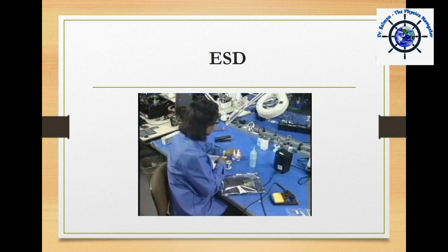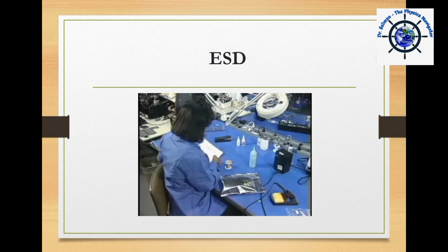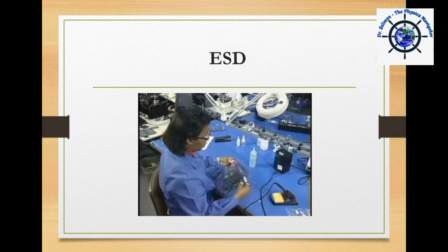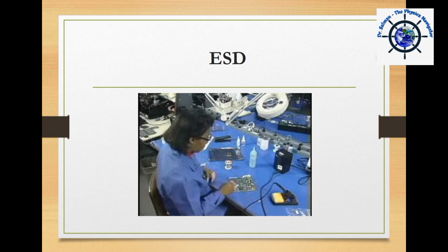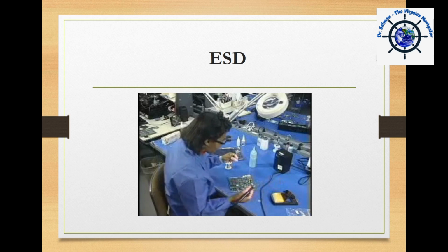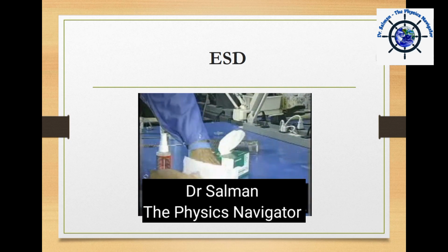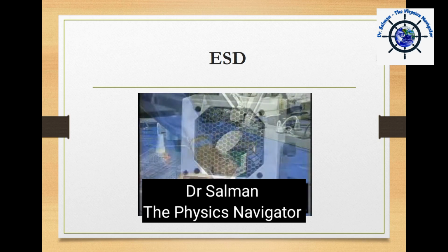If static generating materials are essential for your job, the workstation should be arranged so that static sensitive assemblies are never closer than 12 inches to the static generating materials. There are several methods available for reducing the effect these items will have at the workstation. For example, you may be required to apply an anti-static solution to these hand tools at regular intervals.